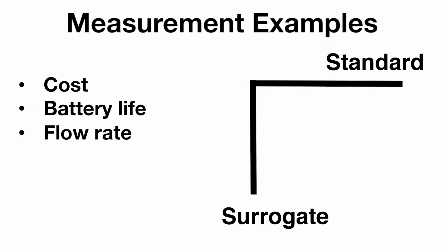It may take too long to measure the full battery life of a product, so the team may look up a value in the literature. Finally, a team may measure the filtration rate for their device over the course of a week and then extrapolate its performance over a month. For battery life, a team may complete a series of measurements with their device and measure depletion of the battery during those tests. The team could then extrapolate that depletion to estimate the overall length of the battery life.